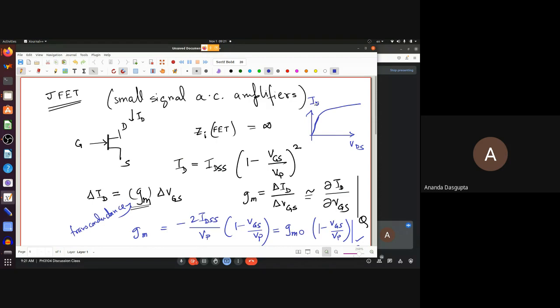This, of course, is the formula once pinch off has occurred, so once ID is saturated. So this is the kind of behavior you get. But I've deliberately drawn these lines, okay, it was more because of my poor drawing skills, but I can now claim legitimately, at least after the fact, that I've deliberately drawn these lines to have a slight upward slope.